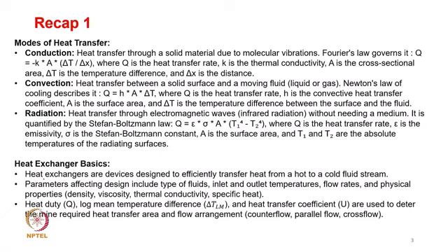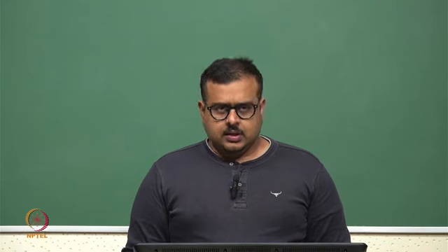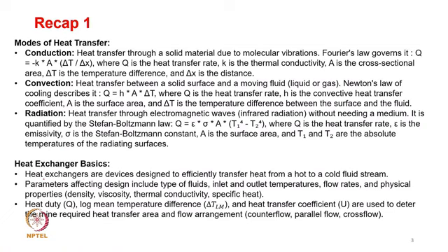Maybe just to get a hang on what we have done in the last 3-4 classes, we will do a quick recap. The first class was all about heat transfer and heat exchangers. There are various modes of heat transfer: conduction, convection, and of course radiation. Conduction is heat transfer through a solid material through molecular vibration, and the governing rule here is the Fourier law of heat conduction.